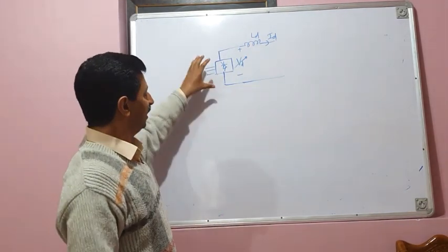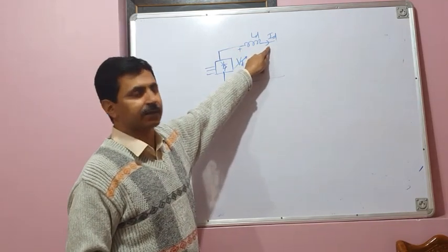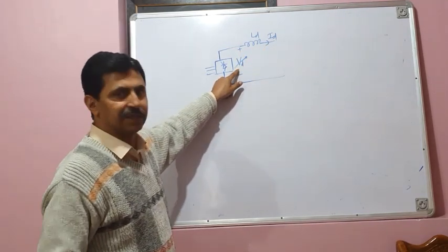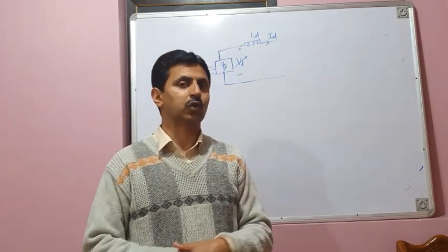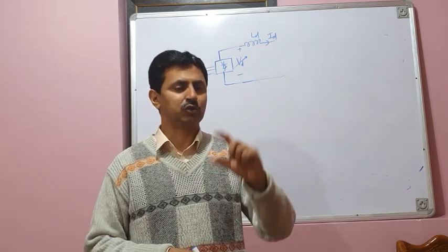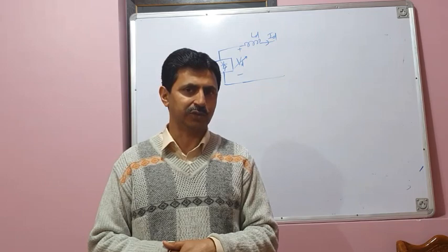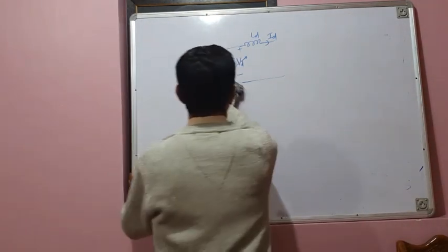That is why in current source converters, we always maintain DC line current constant, whereas we can very easily vary voltage for control of the power. And it is very easy to control the voltage using firing angle control or delay angle control. Okay. So that was about the first part, converters.